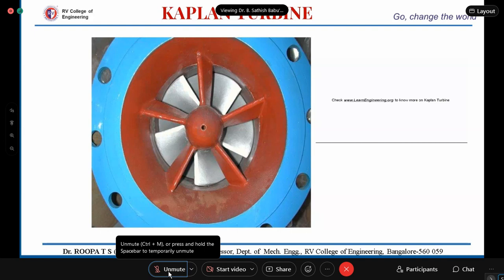Okay, so was it clear? Yes, ma'am. Okay, so in these reaction turbines, the angle of attack and flow control are the two things which need to be monitored very closely, because the swirling effect may decrease the efficiency of the turbine.